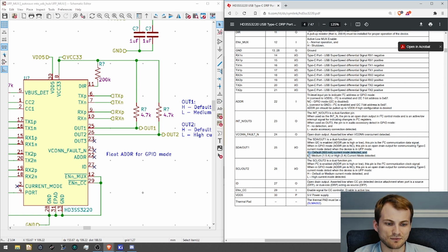But then they give you the logic diagram as high and low, which an open drain can only float or go low. So either this was supposed to be float, or I guess only GPIO mode is an open drain. Either way, it's wrong the way that they wrote it. So my assumption is this is just supposed to be floating, and they're assuming that you are going to have pull-ups. So with a pull-up, now the two outputs will read like that.